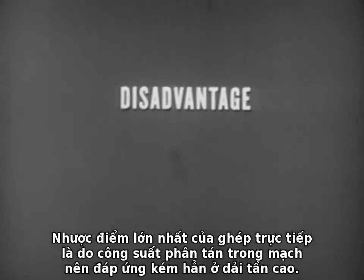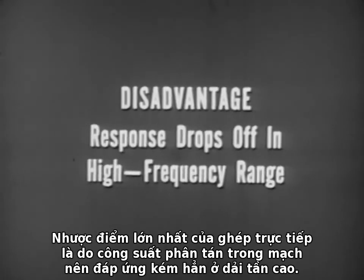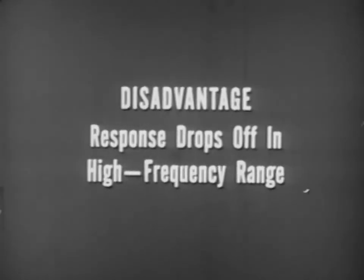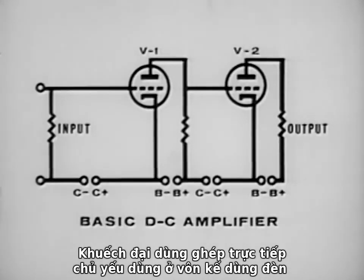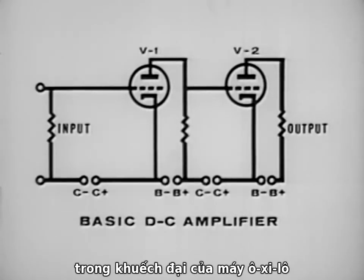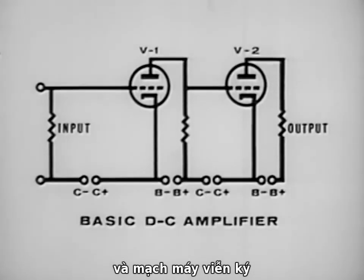The chief disadvantage of DC amplifiers is that due to distributed capacity in the circuit, the response drops off in the high-frequency range. Direct coupled amplifier circuits are used chiefly in vacuum tube voltmeters, in oscilloscope deflection amplifiers, and in radio teletype circuits.